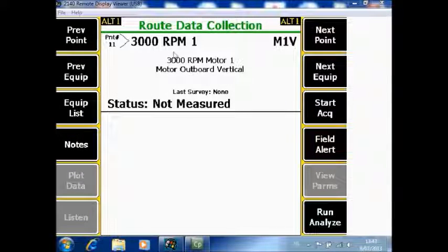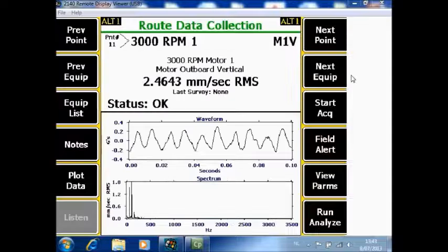Now on purpose the next machine has a speed that is double that of the previous machine, so the Fmax in the root mode will already be more or less double. So let's take a look. We will first collect the regular root data. We push F9 to start acquisition, and a spectrum roughly up to 3500 Hz is measured.